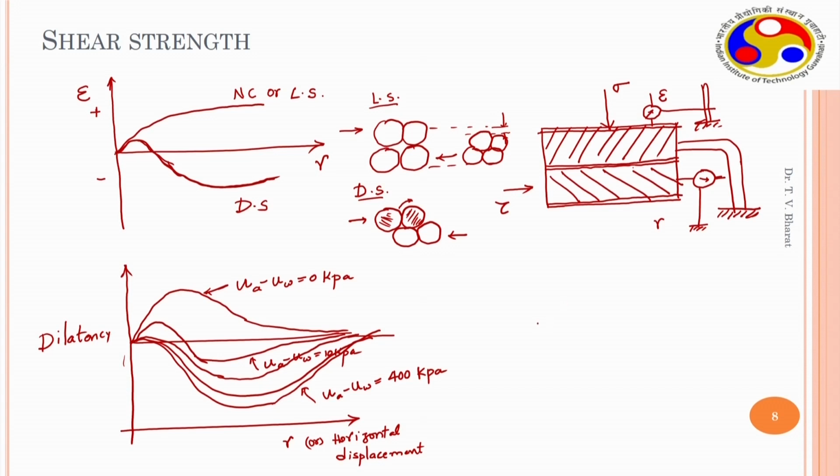Here also, whatever the condition the sample is initially in, when the soil is in a looser state it exhibited similar behavior, but when it has some suction, that is, some water is present within the soil, then when we are shearing, the particles have to overcome the tensile stresses or tension within the pores, because of which it initially shows an increase in the shear stresses.